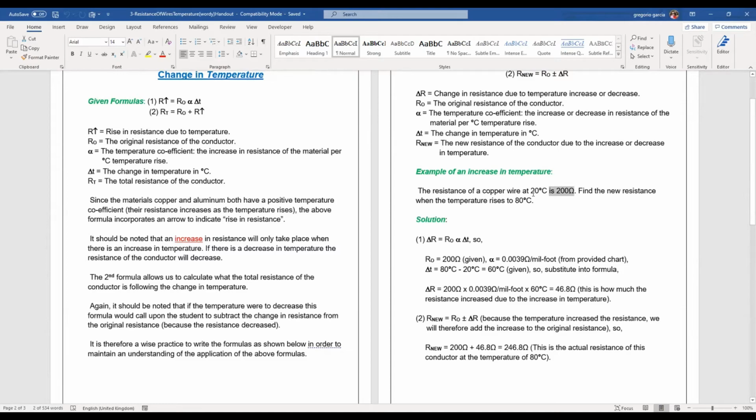That's why every time the temperature goes up, like if the ambient temperature goes up, you apply table 5A. Why? Because the amount of resistance that you have in the wire is going to increase proportionally to the increase in temperature.